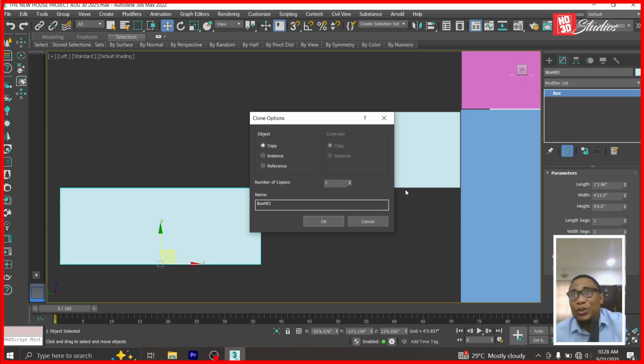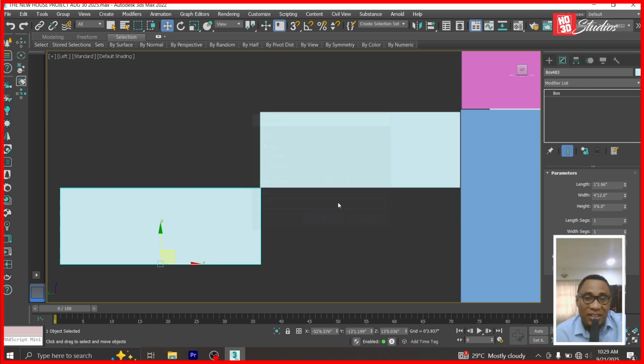Now, one thing I know is that my floor to floor height is 14 feet. If you check the old videos, you would know. So now I'm making one stair, 0.5 of a foot. So that naturally means that I'm going to need about 28 of this. It means 2 of this would make 1 foot. So now, just to be safe, I'm going to do 30 copies.